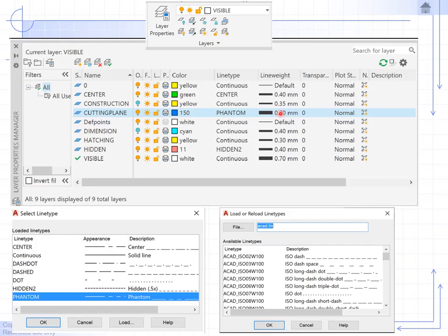You're also going to want to create a hatching layer. So you're going to pick a hatching pattern. So might as well create its own layer for hatching. Click on the create new layer icon, and it'll load it. Name it hatching. Click on the box to change the color. The line type you want to use is continuous, and you want to keep it at 0.30 millimeter in line weight and thickness, same as a center line or a hidden line.